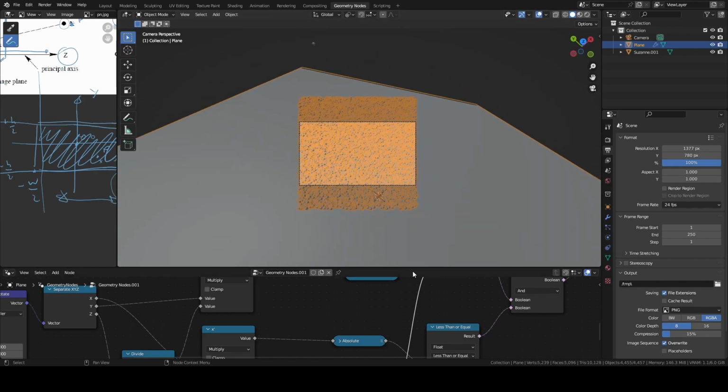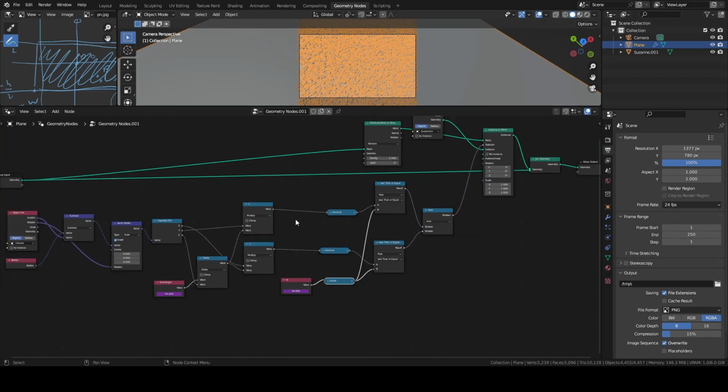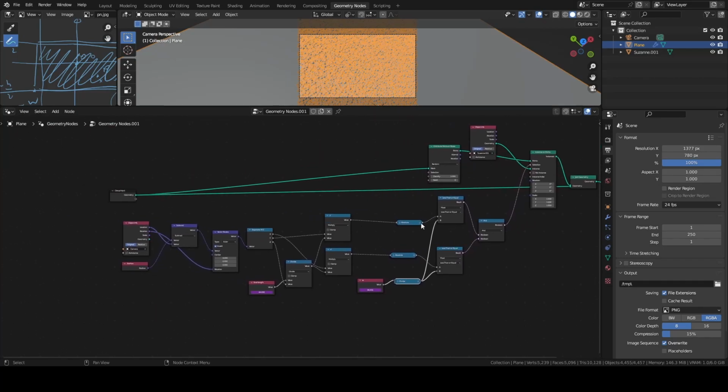So basically that's it. The only problem I see in this configuration, but this is a common problem for everyone, is that if you want to use another camera, or maybe you just want to reuse this node setup in another project, the best solution would be to just append this graph in a new project without modifying the geometry node itself.